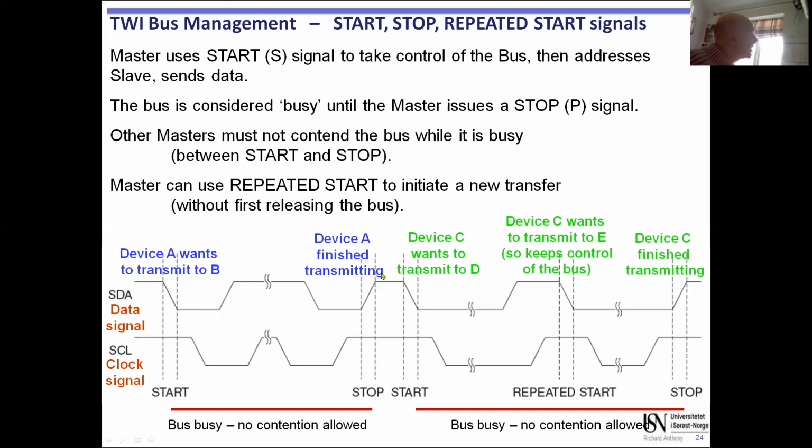When the other changes all occur when the clock signal is low. And this is how the clock also works, because you know that is a data signal because the clock is low. Remember we said earlier, the clock signal goes either high or low to signify data is changing. It's a new data value. So every time a new data value occurs, the clock will go low, and then that will be either a 1 or a 0. That is the actual data because the clock is low.